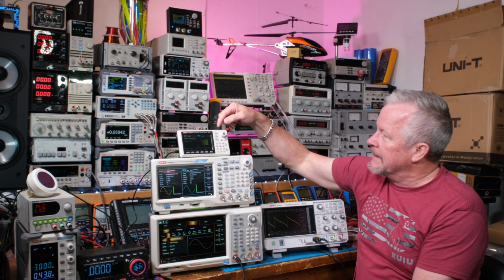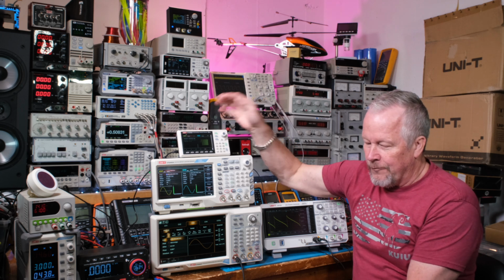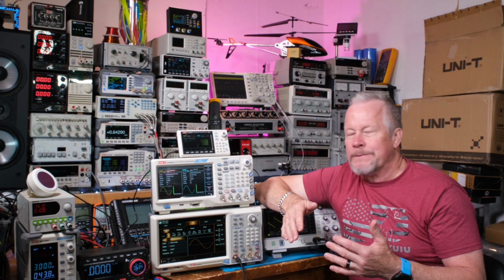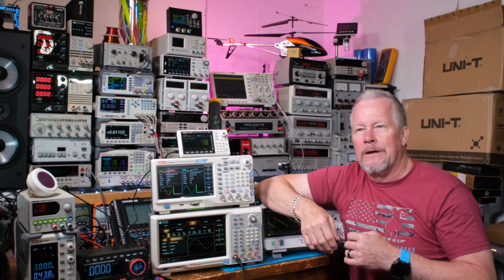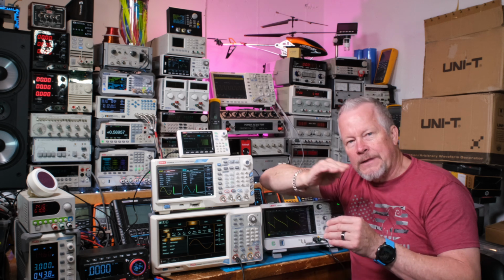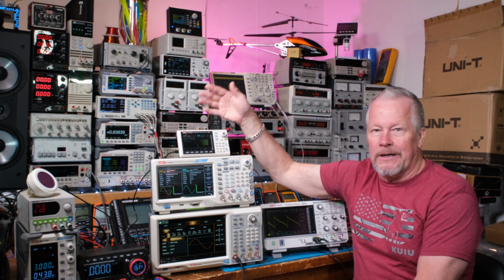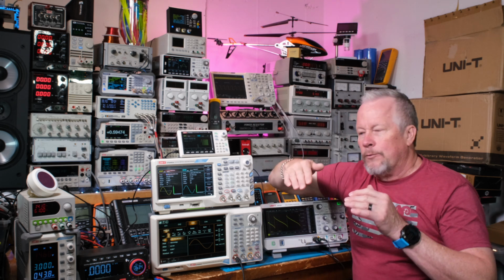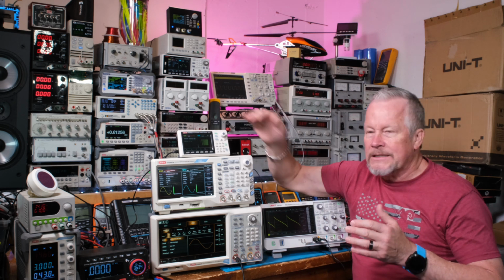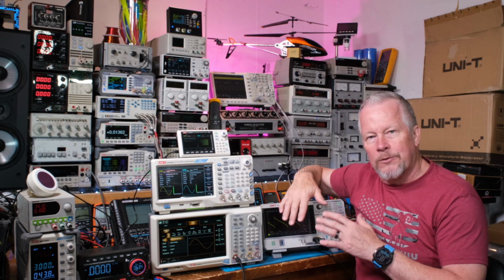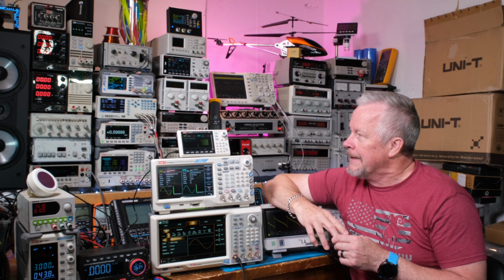This guy here is 14 bits, okay? 14 bits is crazy. Like the new 12-bit scopes, this is 14. So the new 12-bit scopes went up to 4,000 steps. This guy is essentially 4 times more. It's a little over 16,000 steps. So that's why with, say, an 8-bit scope, it's hard to see those staircases, because they're so small in comparison to the resolution of the scope, you know?